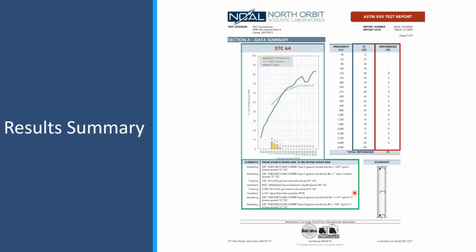So I've done other presentations on steel studs and the effect of mill thickness and stud gauge. So if you want a deeper dive into that, you can go check out those presentations. But just generally speaking, the stiffer the stud, so the thicker the steel, the more sound that it transmits and the lower acoustical performance that you tend to get, all other things being equal. Again, older reports, older versions of like the Gypsum Association Fire and Sound Design Manual would often just list steel studs as steel studs without any sort of reference to gauge or mill thickness.